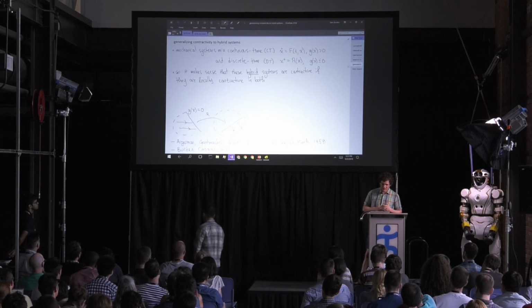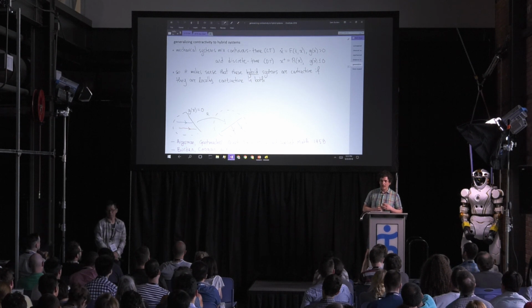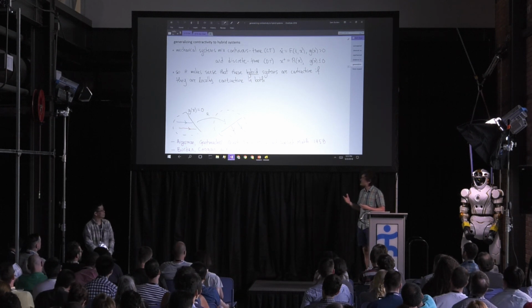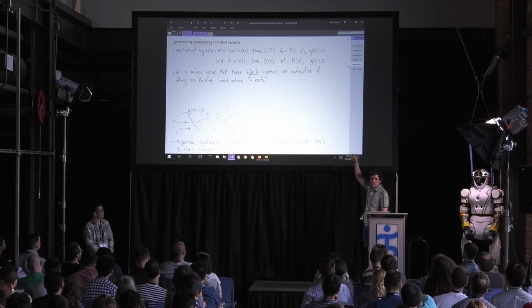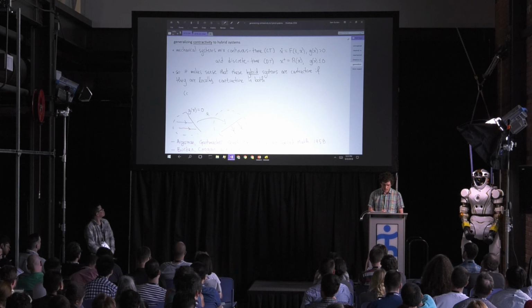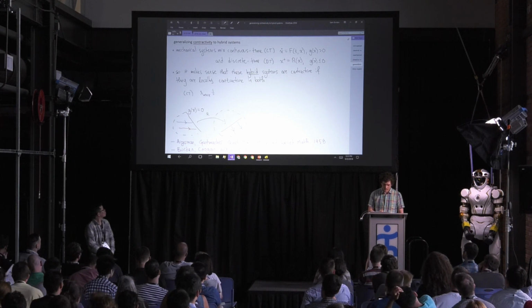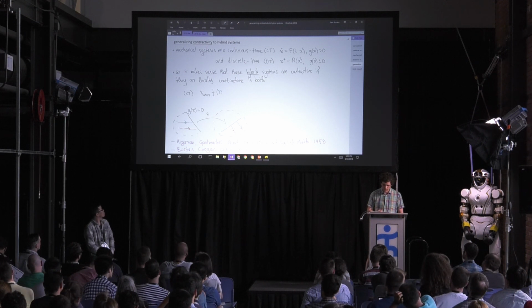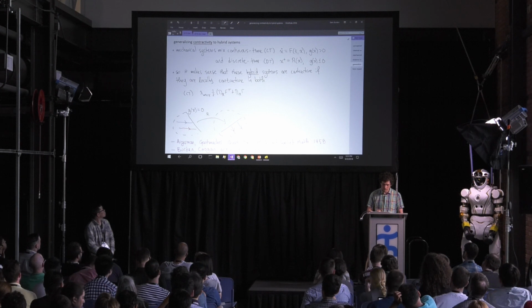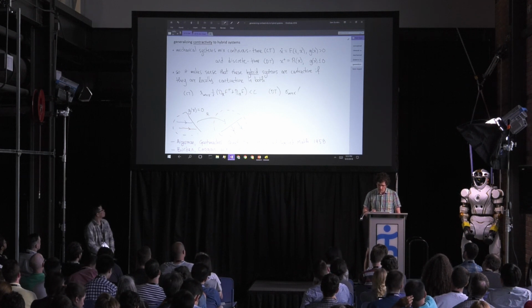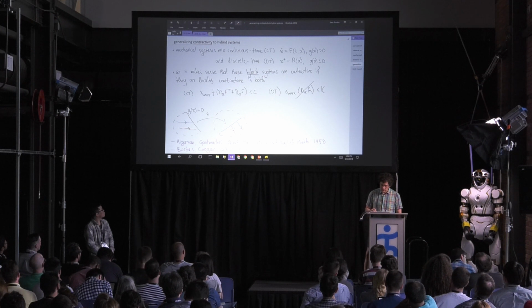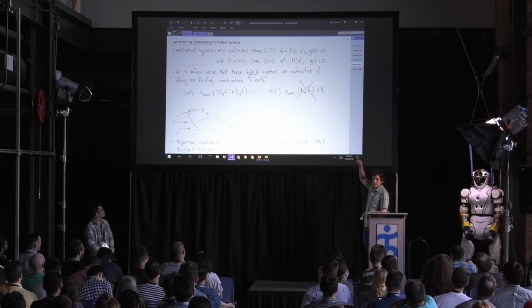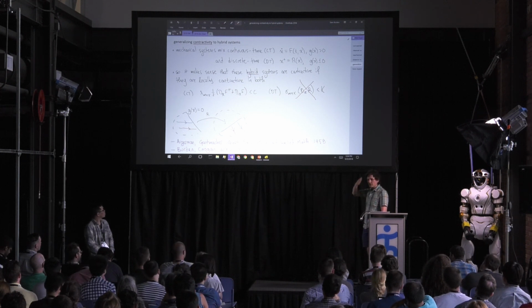So now that I have the right notion of distance in my pocket, I want to generalize this to hybrid systems, meaning piecewise defined dynamical systems that govern the kind of mechanical systems I'm interested in. It would make sense, since I showed continuous time systems before and discrete time systems before, that if you want the hybrid system to be contractive, then you want it to be contractive in continuous time. So you want lambda max, the maximum eigenvalue of the symmetric part of the Jacobian, to be less than c. I know that I'm running out of time. And then in discrete time, one might imagine that you would want the maximum singular value of the Jacobian of your discrete time map to be bounded by k. But this second thing turns out to be wrong. And it's wrong because of the guard condition, the interaction with the ground and the geometry of the surface and your flow to get there.